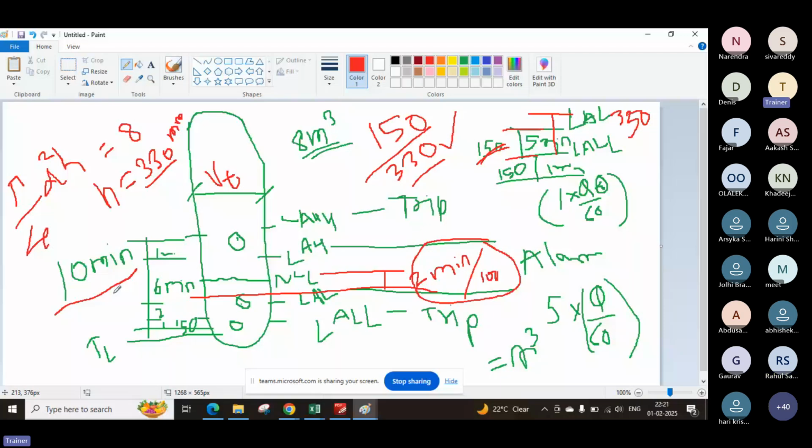Once we design the equipment, suppose you are running, take an example of an offshore platform. In the early stages, your oil or liquid flow rates will be very high. But over the life of the well or platform, the liquid level will go down, water content will go high, and the gas will also go down. The pressure will also go down. But the dimensions of the equipment remain the same across the life, irrespective of the liquid level going up and down. So in that case, we change the level settings, but the diameter and the length remain the same.